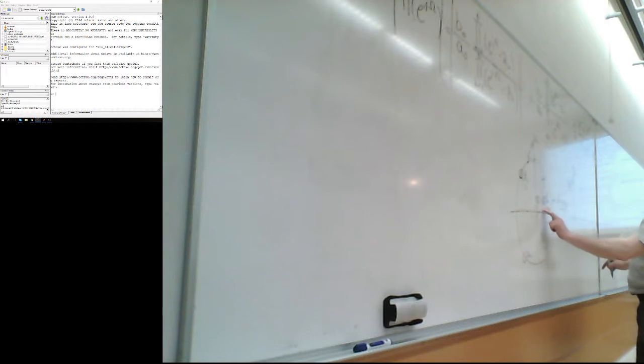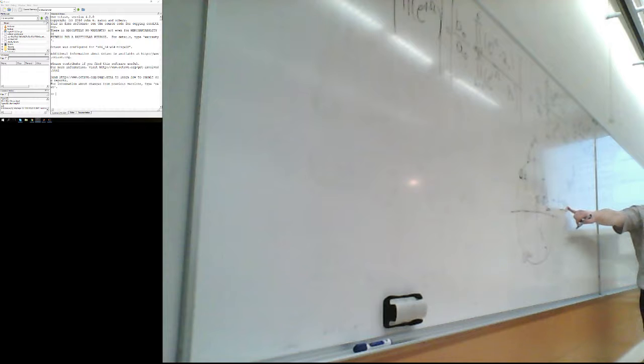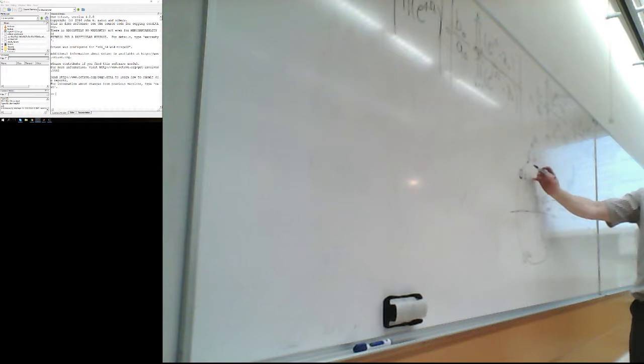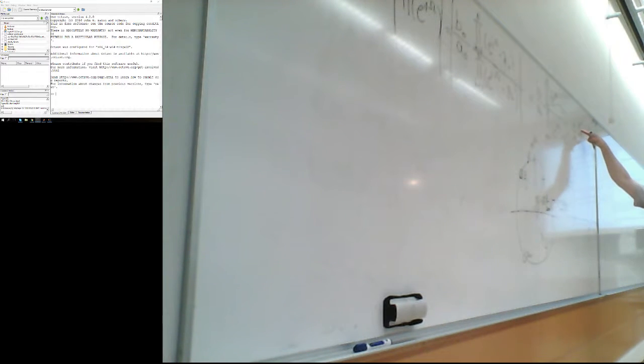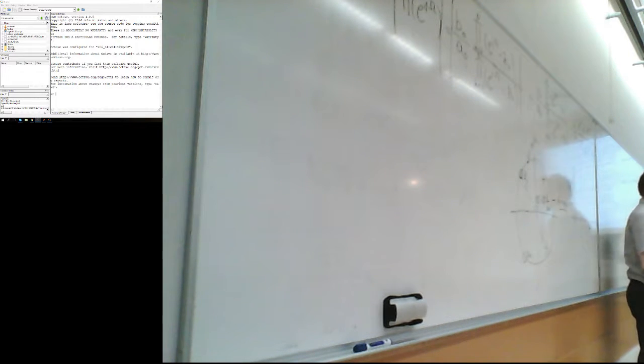At that point, 3 pi over 4, which is 750 hertz, this is 0. The distance is 0 because it's exactly at the same point as the zero on the unit circle, so the amplitude response is 0. In our graph it was logarithmic, so it means it has minus a few hundred dB.